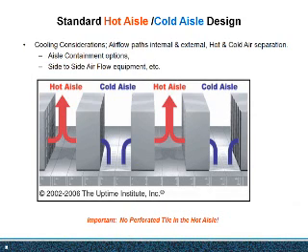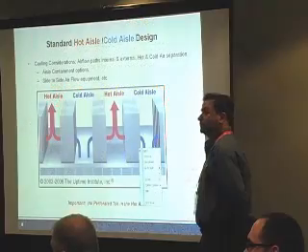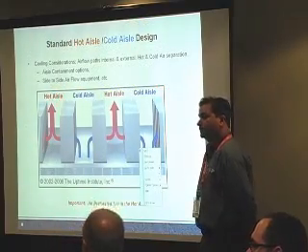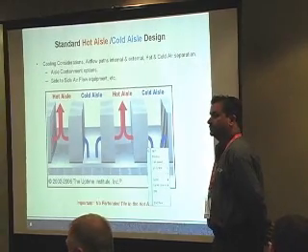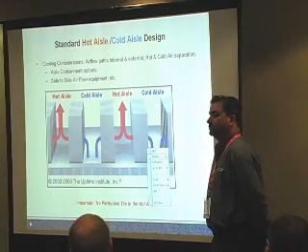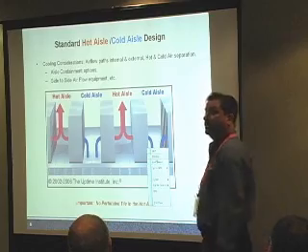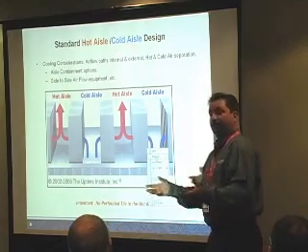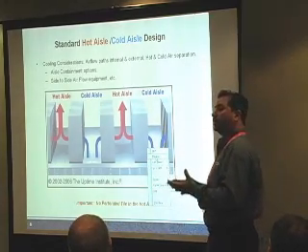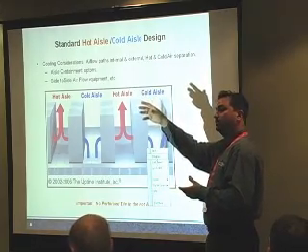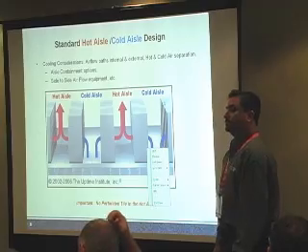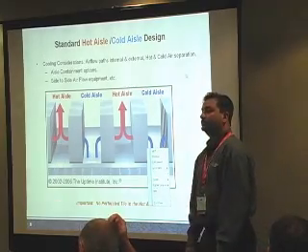If you go into an area and set up a unit or a room like this, and you duct your hot air up into a ceiling space, how do you exhaust that hot air in that existing ceiling space? The CRAC unit has to make some type of provision for that. The CRAC unit is the building, and when they're building that facility, they are ducting, they're drawing in from that. This facility is already built, and you have no provision for that. How do you get it out? You have to make provision somehow?